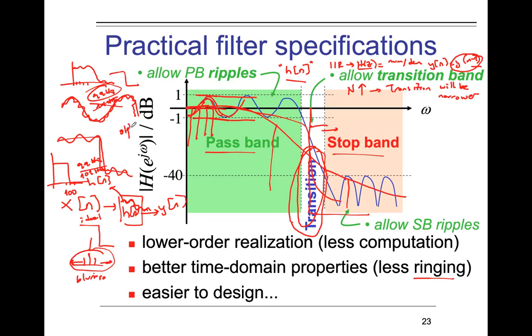Okay. But for example, arkadaşlar, you have an alpha wave filter. What is the cutoff frequency? Let's say between 8 and 13 hertz, right? Değil mi? 7 to 13, 7 to 12, 8 to 13, something like that. Okay. So you have a band pass filter. If it is not sharp, what will the band pass filter be like? Like this.